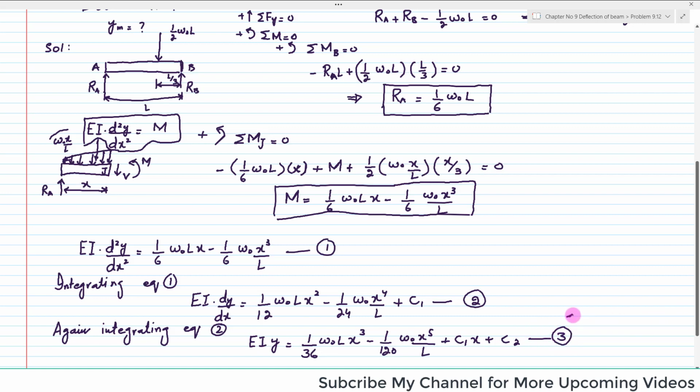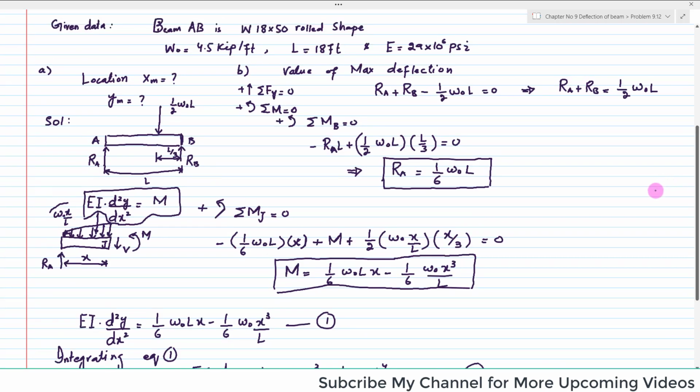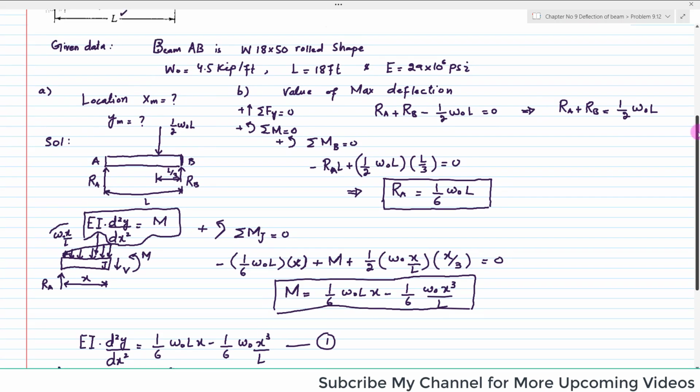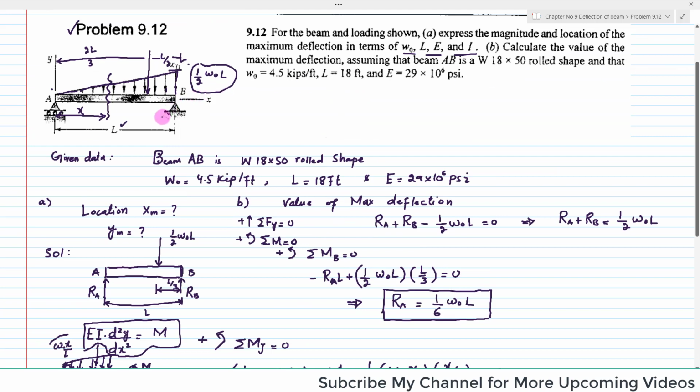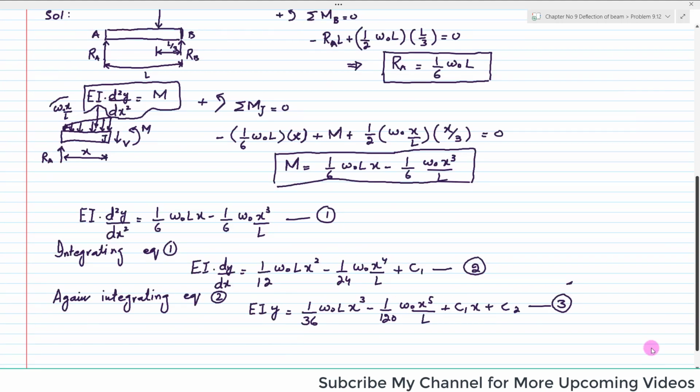So in order to find these, we will use the boundary conditions. So what will be the boundary conditions? Let me show you the beam. So you can see both ends of the beam are supported. So at x is equal to 0, y is equal to 0, and at x is equal to L, again y is equal to 0. So these are the boundary conditions that will be used below to find C1 and C2.